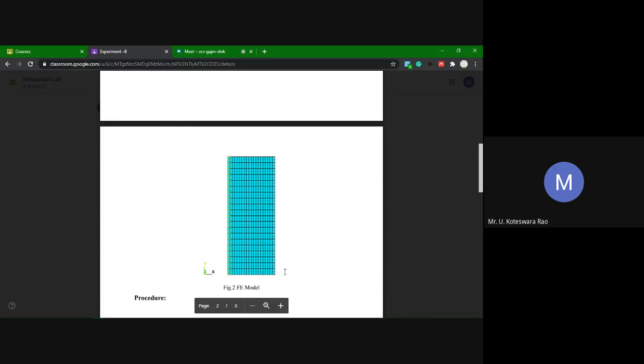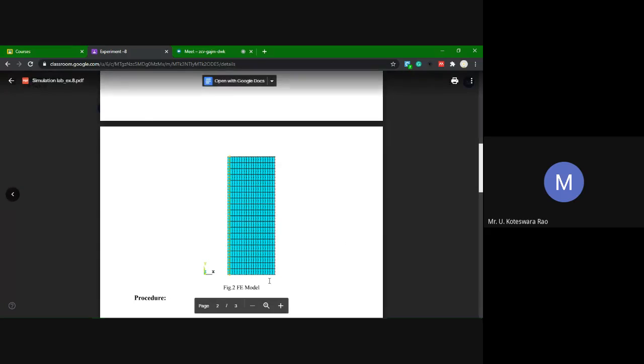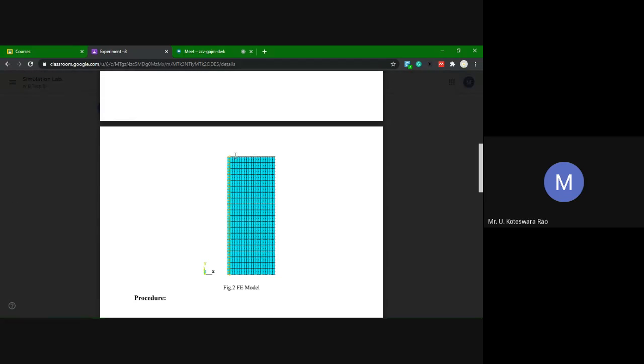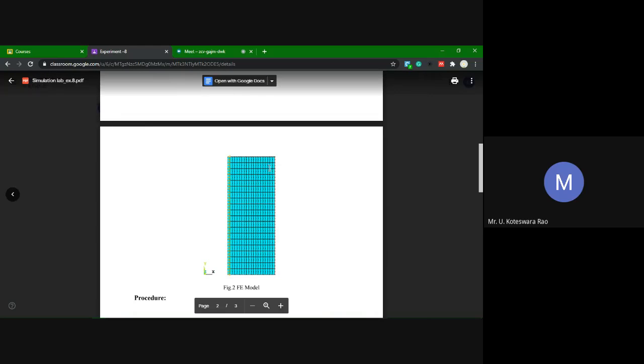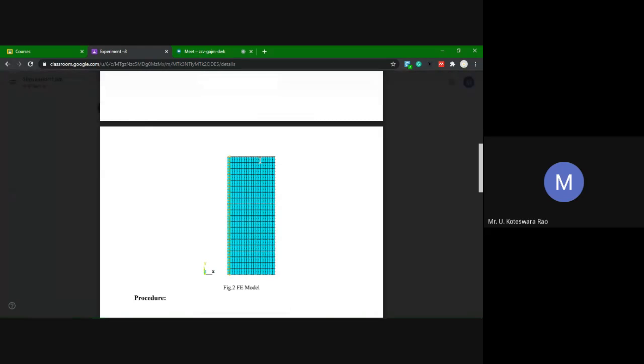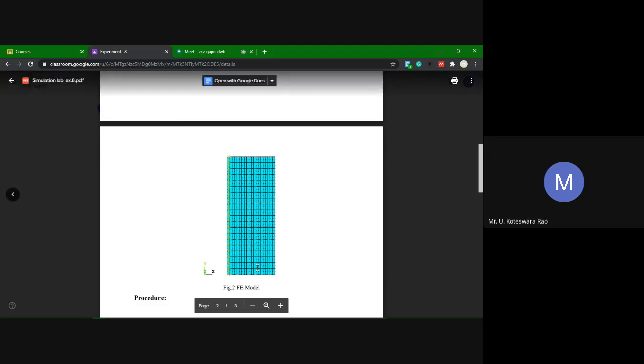And this is the outer surface. You can see the red line here. This red line indicates the convection boundary condition, so this surface is subjected to convection. We need to apply that also. And since we are choosing the length of the cylinder randomly, on the top and on the bottom you need to apply an insulation boundary condition. Insulation boundary condition means the amount of heat flux crossing this boundary, as well as the other boundary, is 0.